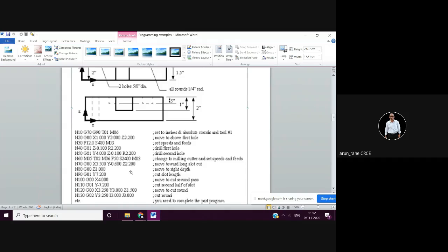Reset. Okay, so M05 enter, M09 enter. Enter means next block. Then G28, G91, X0, Y0, Z0, M06, tool number 2. Then the fourth block, you can say M03, S2400 and F50. That is, you are starting the spindle. Now where are you starting the spindle? At the reference position. Actually, it is not good.